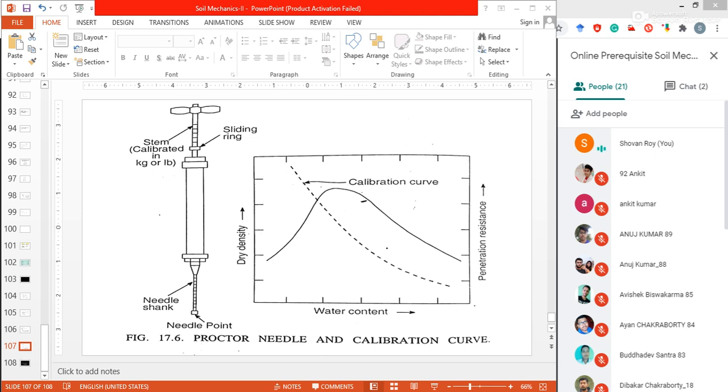The field kit contains the moisture tester, a small single pan weighing balance, a bottle containing calcium carbide, and a brush. A big container permits the use of 26 gram sample. In order that balls having wet soil inside the dry soil outside may not form during the reaction with calcium carbide, the soil may be mixed with perfectly dry sand.